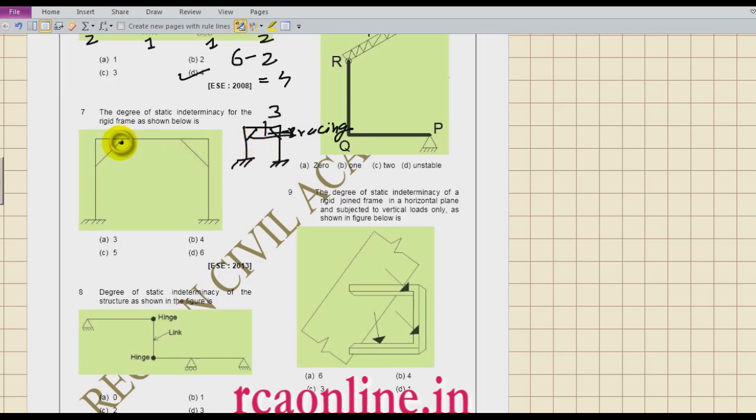So they have the internal hinge at these points, at their own. The internal hinge is not at the junction, but a little bit inside the member, inside the bracing. Is it okay? So I don't get any additional equation, but at the same time I get 2 more unknowns. One unknown is this and one unknown is this. Axial force in these 2. So what will be my static indeterminacy now? 3 for the normal plus 2 because of this and this. So my total is 5.